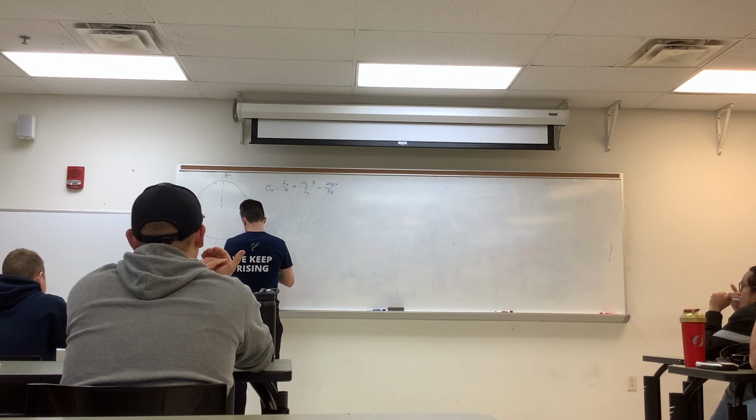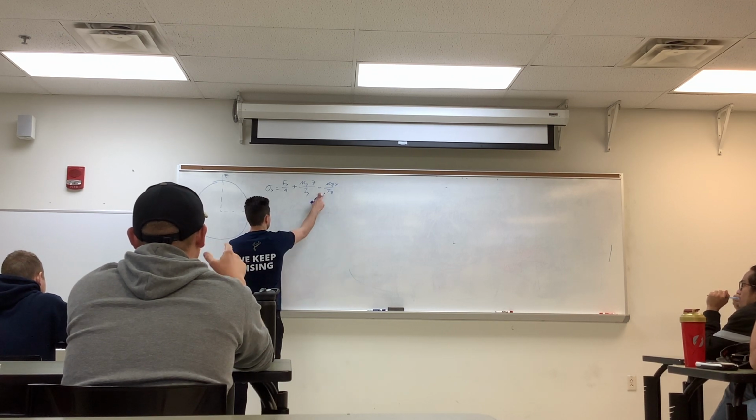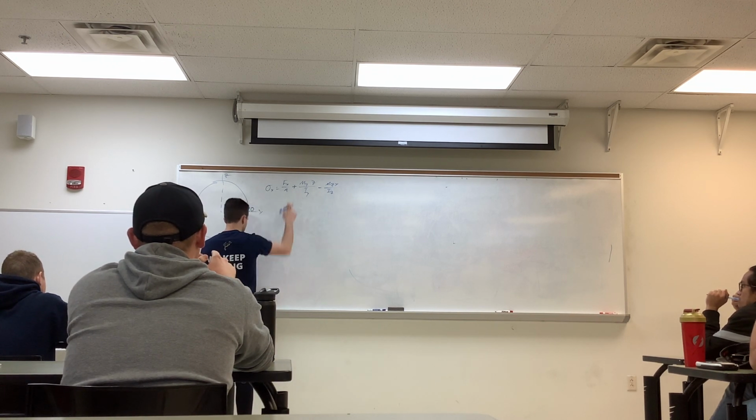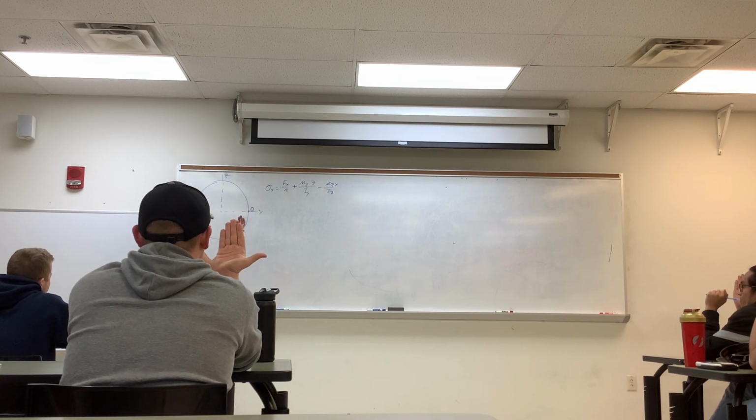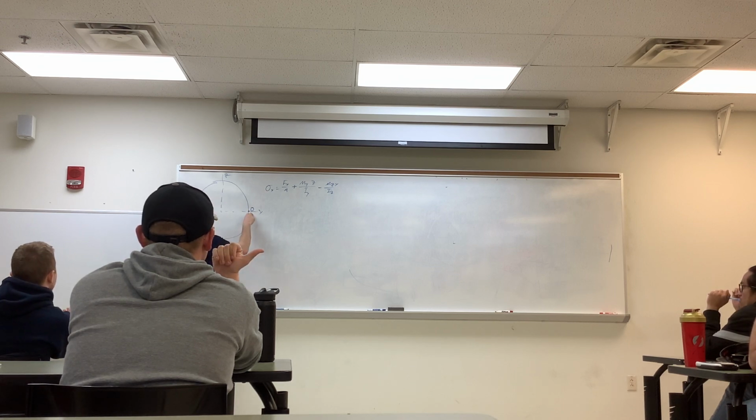Wait, why is the second one positive? The M y z? Yeah. Right-hand rule. If it's along that same plane, or identical along where your thumb is, it'll be positive at that spot. Even though this is along that exact plane, we could take that cut. If it was on the other side, would it be negative? It'd be positive there too. But if it's below, it'll be negative.